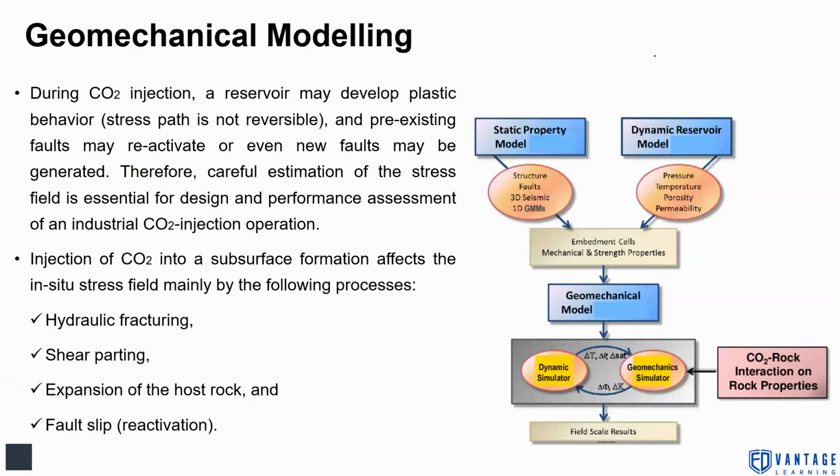Let me draw a fault here, for example. You have a fault like this. Okay. So you can see this is a footwall and hanging wall. If I draw a vertical axis and if I take this, so this is the throw. The equivalent displacement of the fault plane with the vertical axis, and this is called heave. For example, if the throw of the fault is quite high, there can be a stratigraphic discontinuity such that your CO2 may be injected here, might leak and react to the fault.